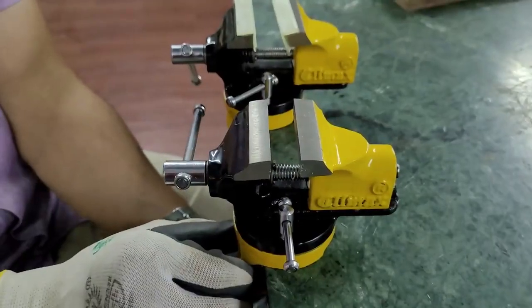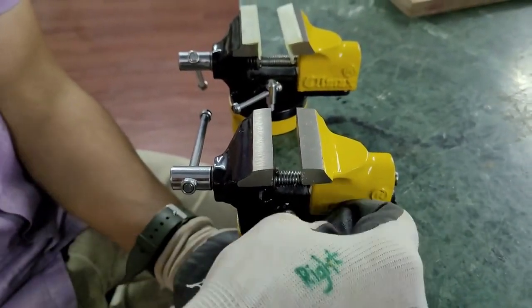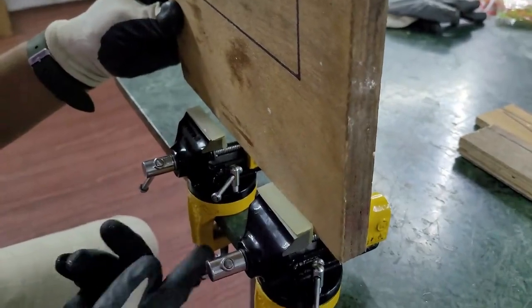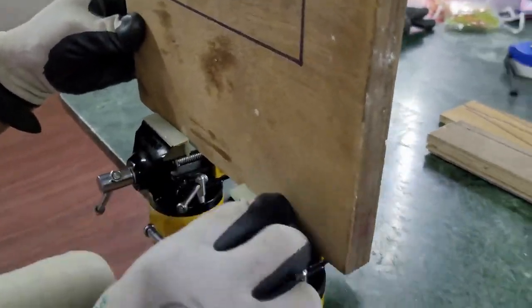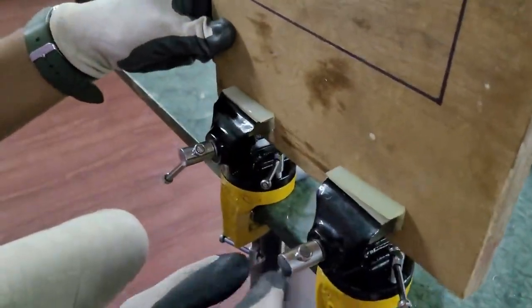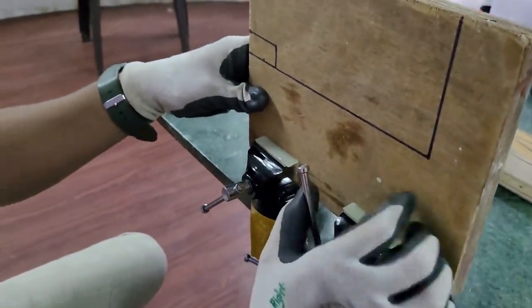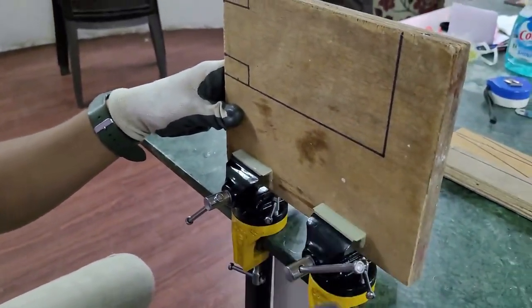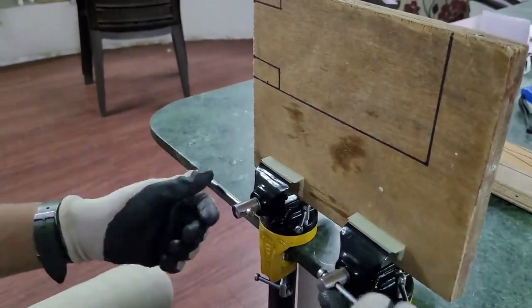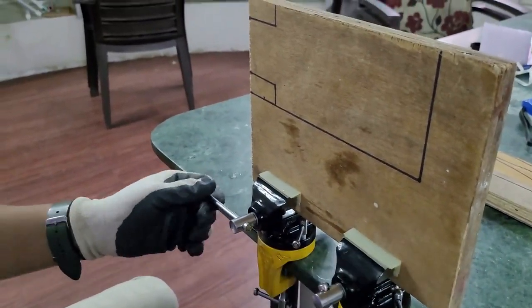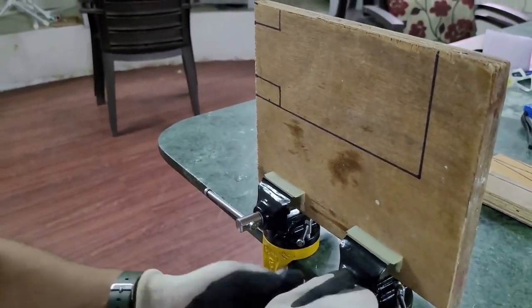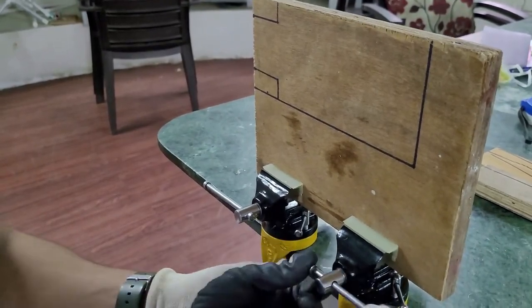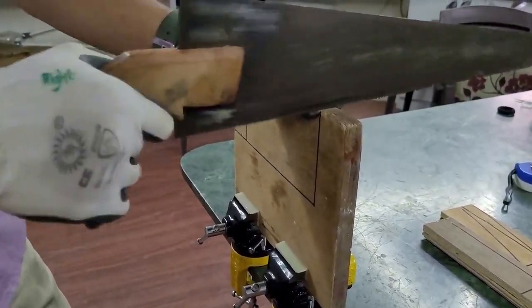adjustable bench vise. We are going to use two of them because some of the wooden boards are longer in length, like this base plate. So it is better to clamp this base plate using two bench vises so it gets proper support like this. So tighten the job properly. Use hand gloves. Keep the base plate upright, and start using the hacksaw.